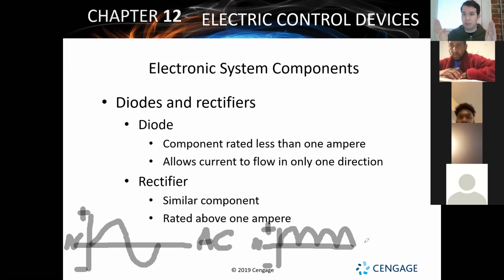It can go from 0 to 100 at 1% at a time, basically. That's the whole thing. It's just very incremental amounts. So as it needs to produce more cooling or more of a refrigeration effect, or as it needs to produce more heat for heating, it can actually react to that based on, hey, what's the temperature outside and what's the temperature inside? How much is the difference? And it learns all of these different things. So that has to do with that DC control.